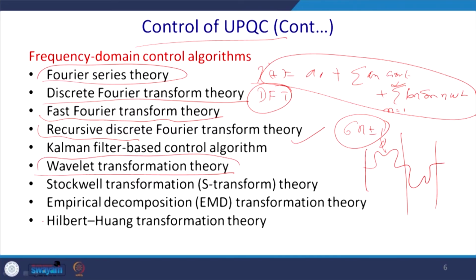So, what happens if there is a load change or a fault occurs, then based on the mother wavelet, the change in pattern can be detected easily. From there we can estimate the magnitude as well as the phase of the current changes, and ultimately we generally do FFT after that to re-verify the actual data.